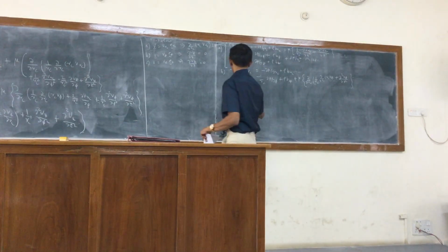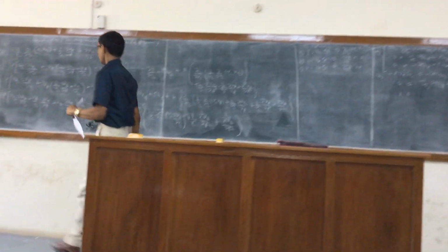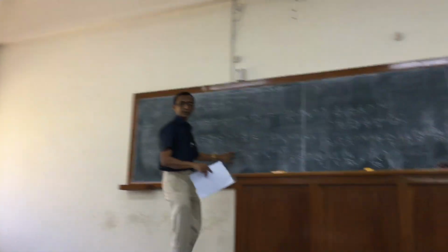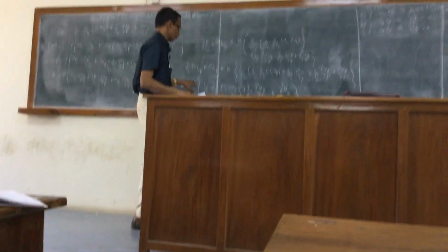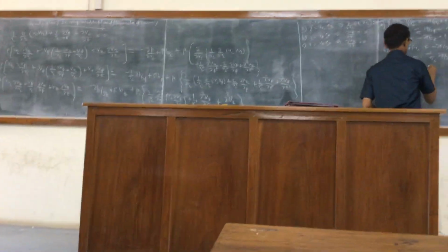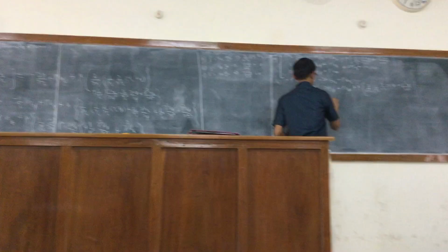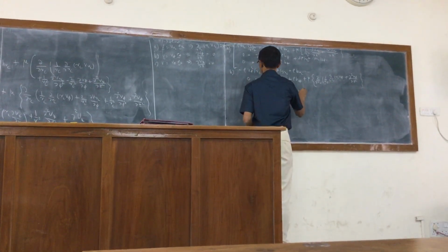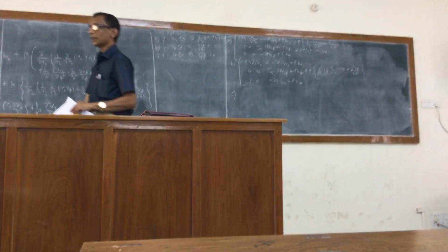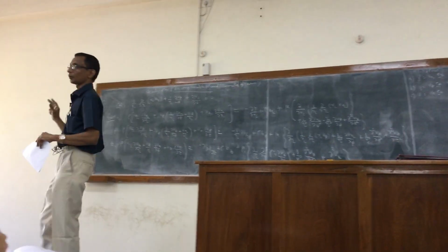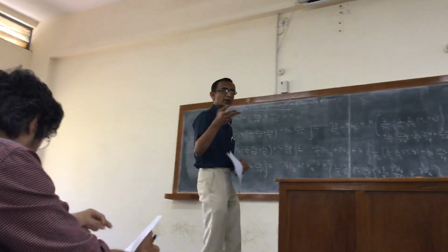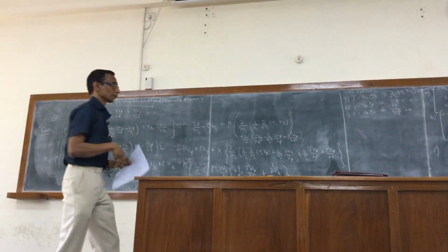And then the third equation will probably be simpler. So d by dz is 0, so all of these terms are 0. V phi is identically independent of z, and so probably none of the terms would contribute, and I would simply get minus dp by dz equals rho g z. So all of these correspond to the equation of motion for case B, where only the phi component is present. Right? So if you write these equations down, then it's easier for you to solve the problems in the assignment.